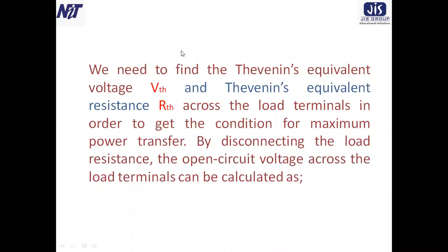So 2 things we have to find out. First one is VTH, that is Thevenin voltage. Second one is RTH, the Thevenin equivalent resistance across the load terminals, in order to get the condition for maximum power transfer.